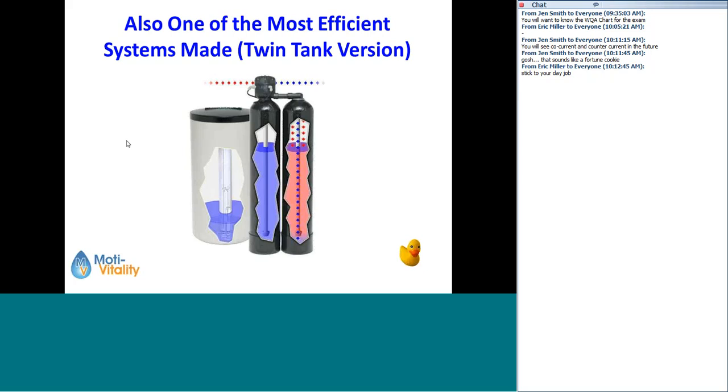So definitely any twin tank system is going to be more efficient than a single tank softener. I can't say way more, because there are some single tank softeners out there now, when you get things like proportional brining, dry brine tank and countercurrent regeneration, that are matching the efficiencies of some of the twin tank systems out there. But definitely in terms of cleaning in soft water, that's an absolute better way of doing it.